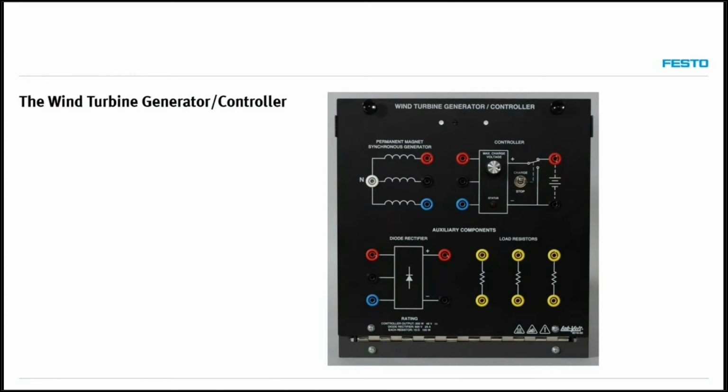Finally, in the upper right corner, there is a controller, which is a battery charge controller, to which you connect the 3-phase output of the wind turbine, and on the right side you connect the battery that you want to charge. This is typical of a home installation where you have your wind turbine connected to a battery to charge it.